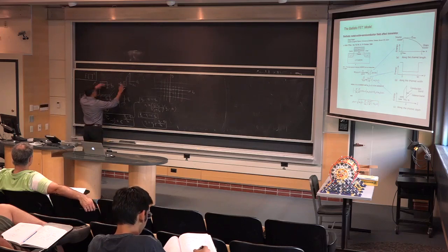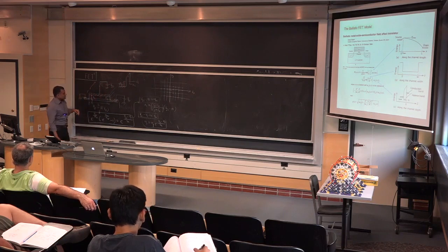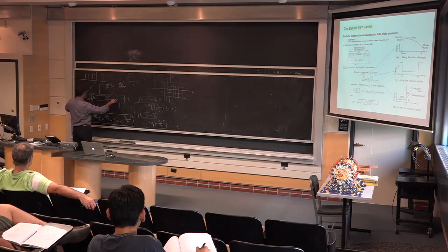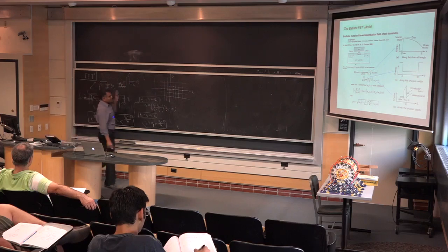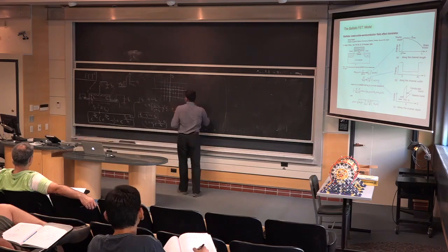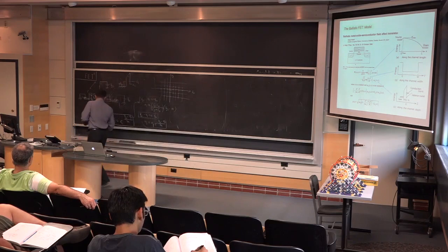So what the gate battery is doing is it's taking electrons away from the metal, right, and it's injecting it into the semiconductor, right? And you can see if these two are shorted, the electrons will be injected from both sides. You see that, right? Equally, if they're shorted. I mean, there's no preference which way. So this is kind of an important picture to realize.